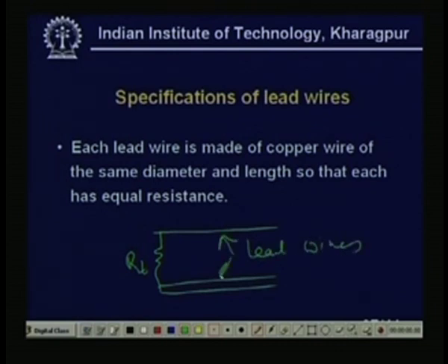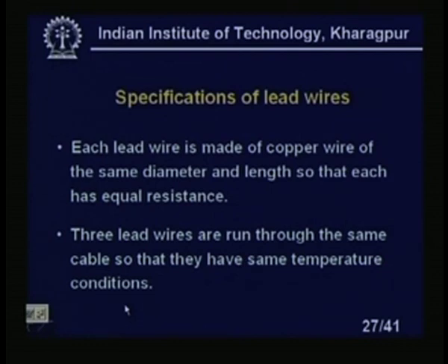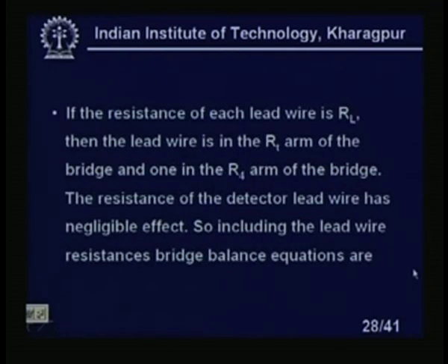The three lead wires are run through the same cable, so that they have the same temperature condition. This is also necessary.